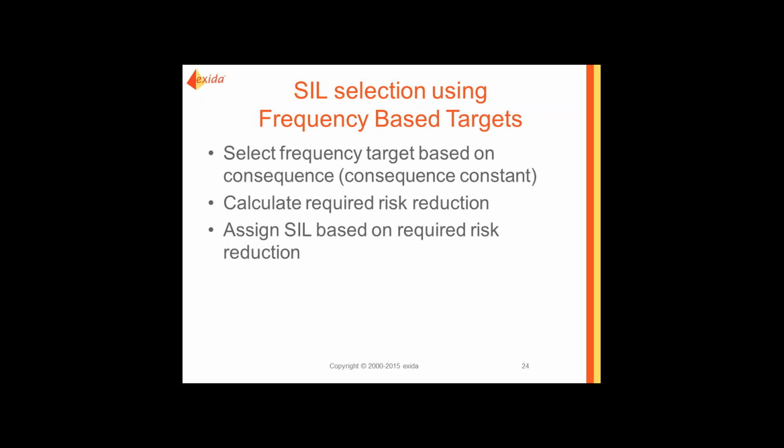However, it's good for a first pass, but you want to be more specific, because as you go up from a SIL1 to a SIL2 to a SIL3, the cost of number 1, designing that, and number 2, maintaining it throughout the life of the SIS is going to be significantly different, especially if you're looking at SIL3. And of course the bands get wider. SIL1 is between 10 and 99, SIL2 is between 100 and 999, and SIL3 is 1,000 to 9,999.